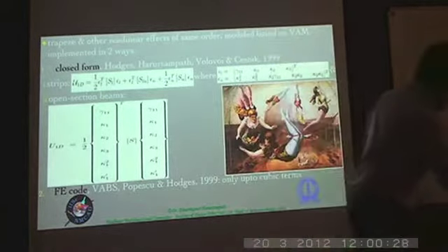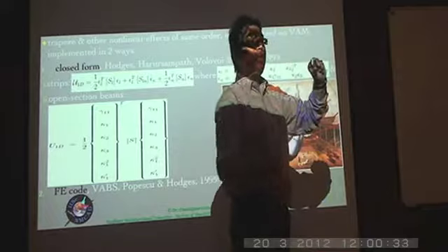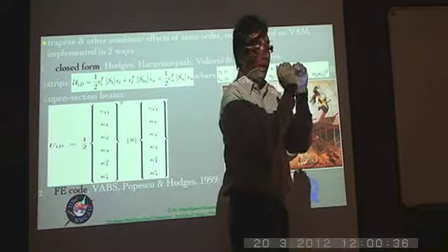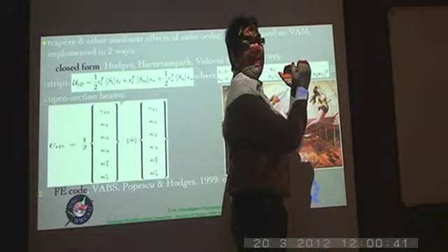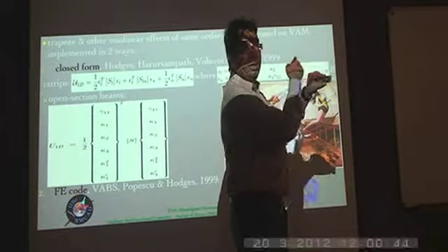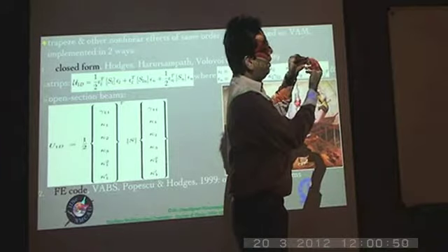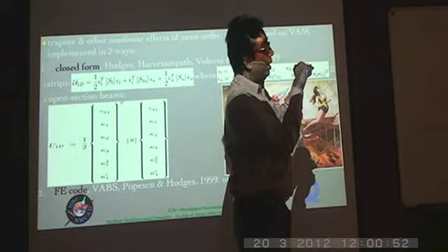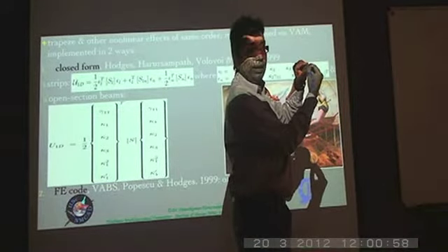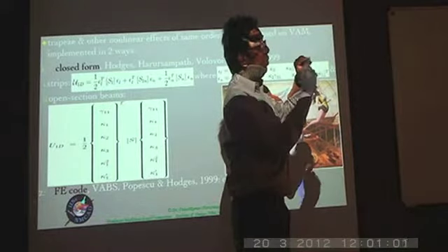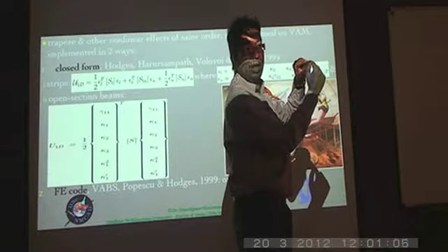So for example, if I am bending this, the strain at any particular location here, suppose it's just an isotropic prismatic beam and there's no coupling and it's the principal axis on which I'm applying these bending moments. Let's say if I apply like this, then it has a certain curvature. Because it's a pure bending moment, it has the same curvature throughout. And now, if I want to determine the strain at any location, I have to determine the neutral axis, which of course for the symmetric section is at the center. And so basically it's the distance from the center, right? So the strain is now proportional to the curvature times the distance from the neutral axis.